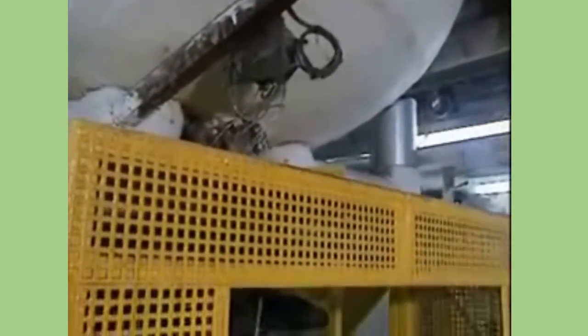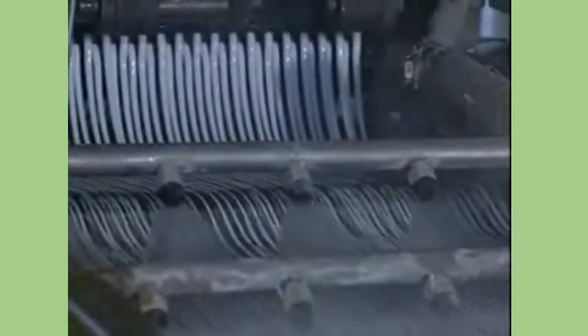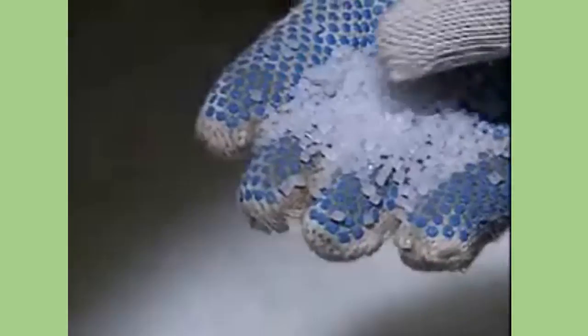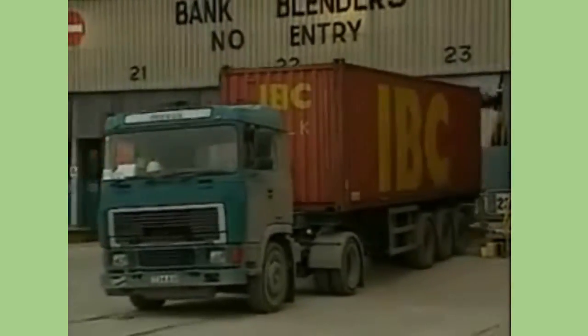When the white nylon is produced, it's molten and is forced through holes to form laces of nylon. The laces are cooled in water and chopped into short lengths about 3 to 4 millimeters long, called granules. Nylon leaves the site in lorries as granules. The granules, which are thermoplastic, will be remelted and moulded or forced through fine holes to make nylon fibres.